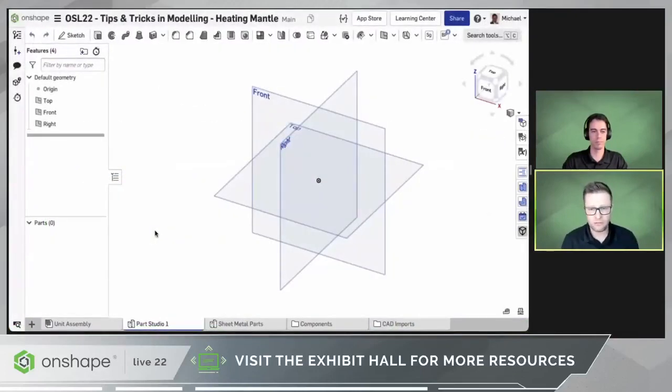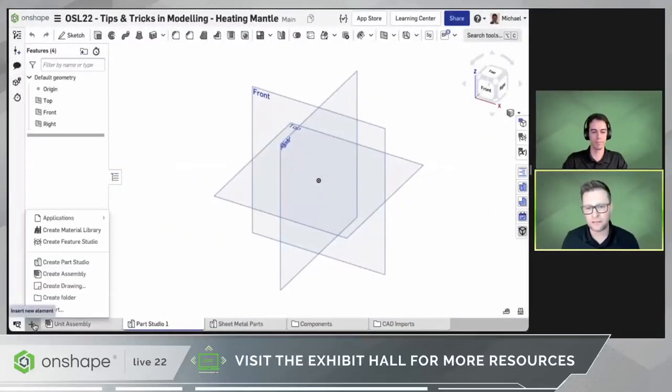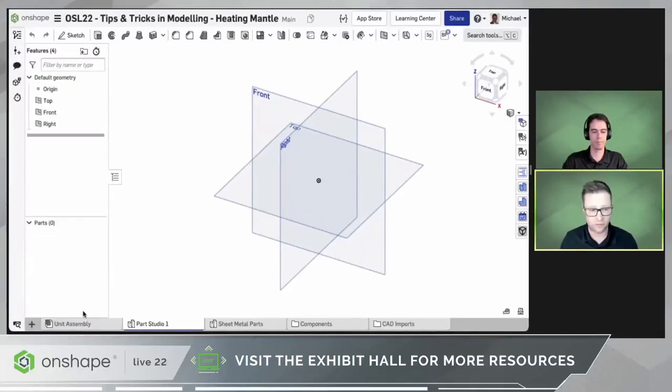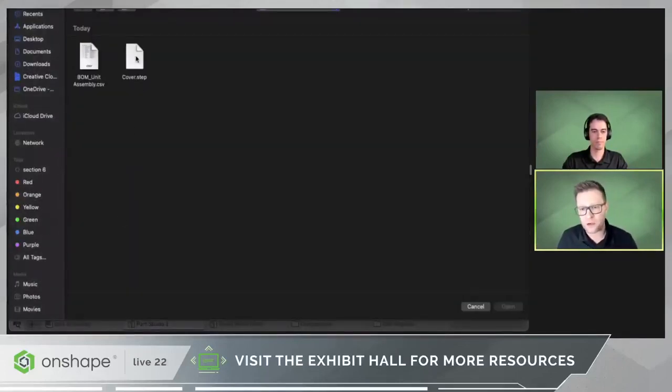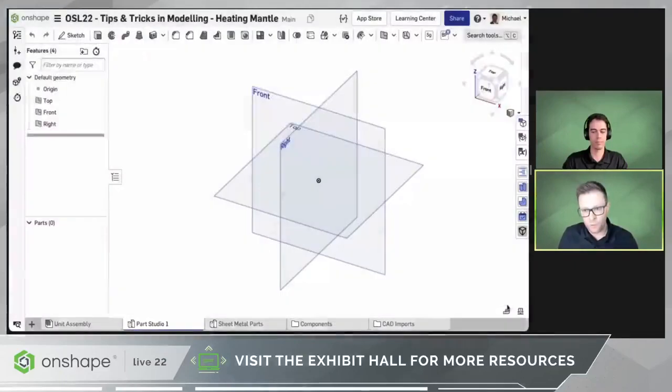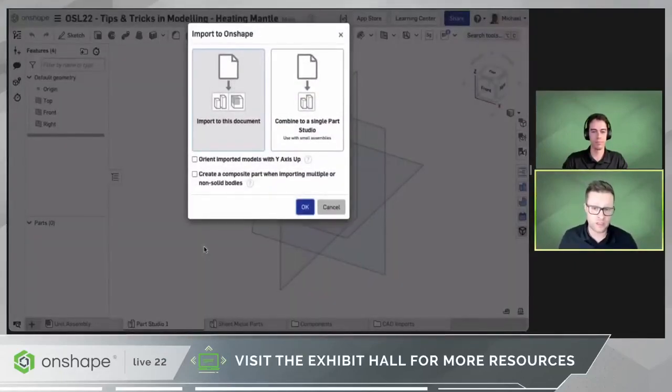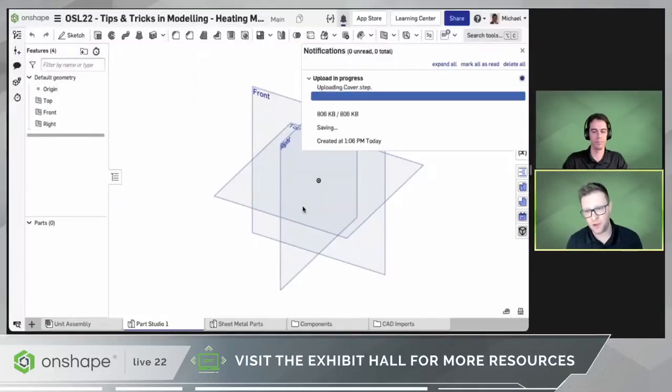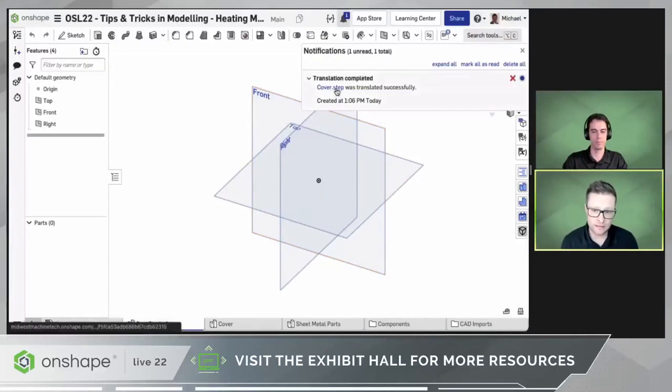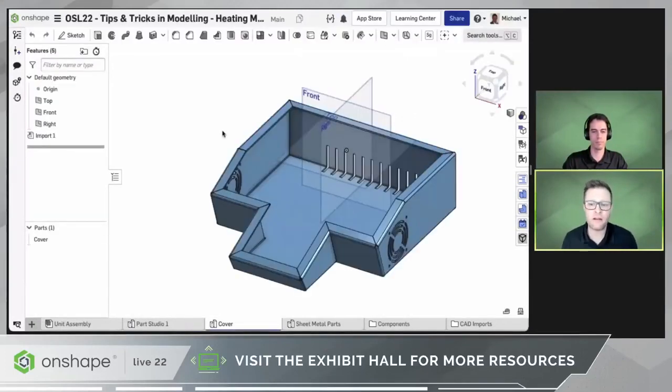So back in Onshape here, let me import a sheet metal part in STEP format from my local hard drive. My first tip for you: once the upload and conversion process in Onshape is complete, a link appears in the notification panel. Clicking on this link opens a document tab and takes me directly to the imported geometry. As we know, there is only one feature, the import feature, but I would like to edit this part and mainly get the flat view out of it.